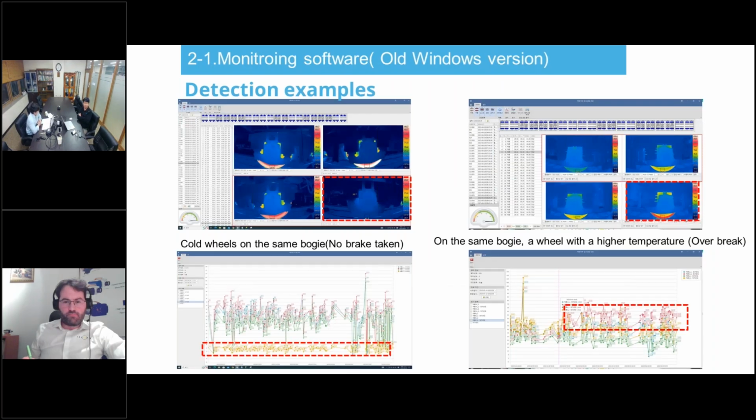Another advantage is that you can prevent accidents in advance by checking trends in the heat distribution chart. If you look at the picture, there are 3 pictures and 1 picture is different. What would be the problem in this case? As you can see, the brake is not taken off. This causes all of the axle brakes to work at once. It's practical.